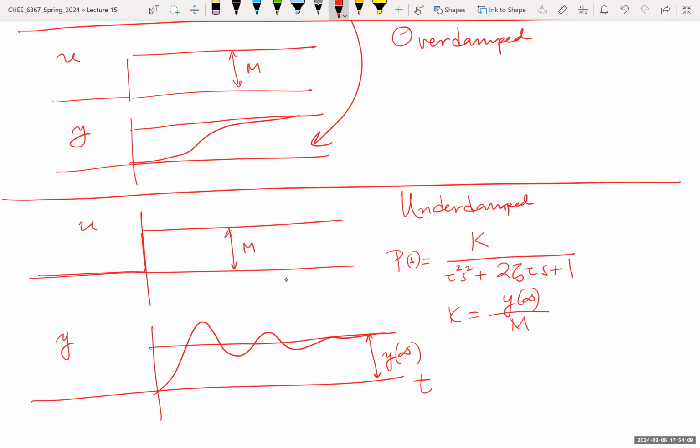Incidentally, when would you see such oscillating dynamics? Well, for chemical engineers, these oscillating dynamics are not very common. You may see these in reactors. That's the one case where those may actually be there. Or they may be induced by feedback control. You may have a simple overdamped process, but the feedback control creates these dynamics, and you may have to identify this entire closed loop like this.